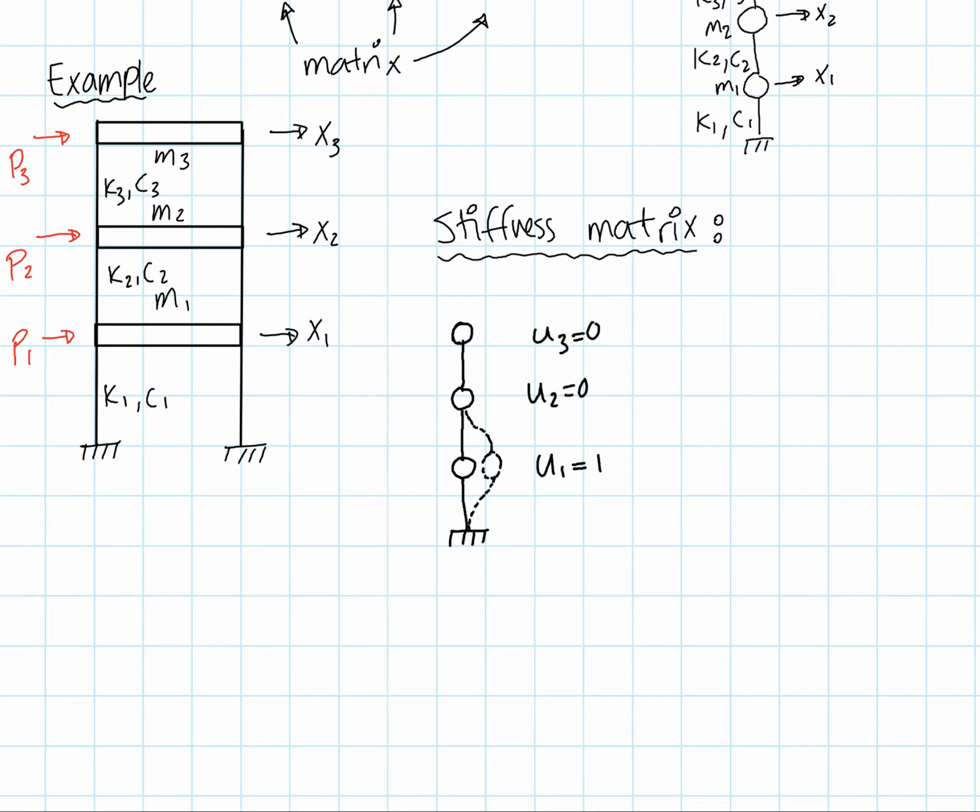Okay, so now that I'm looking for stiffness components, I'm only going to be focused on the stiffness parameters. If I want to find out the resultant force as a byproduct of this unity displacement, I'm going to put an F1 here, and F1 is really standing for that resultant force. And I'm going to have an F2 here that is sort of countering that, and the force on the ground doesn't really matter.